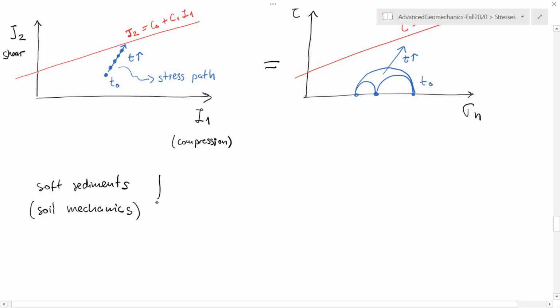And in this case, the most popular definition or characteristic values for the stress tensor are P prime, which in this case is just equal to the mean stress, and remember that this one is effective stress. This is very important. You're going to find also in several books that effective stress is usually denoted with this prime.